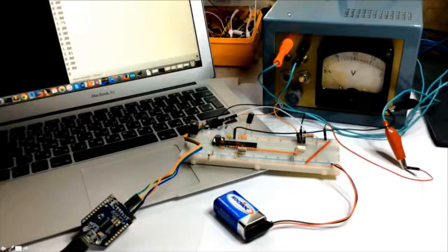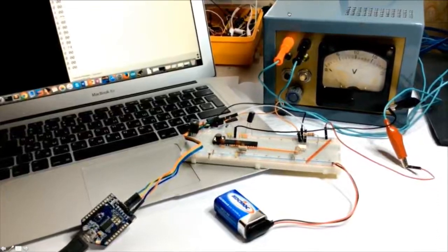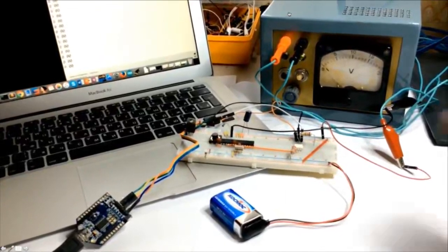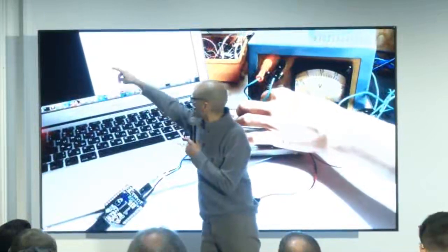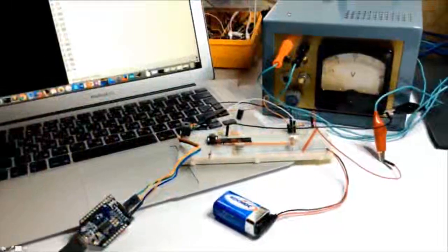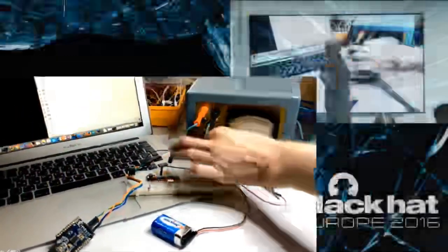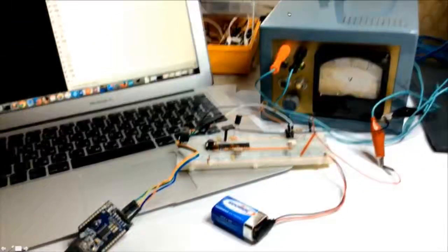And this one is actually only plain. It's a different ADC, integrated in one board. So here we have the 4 or 5 channels connected. The 5 volts is the reference, and then when we start injecting the negative value, we see that there are some weird readings on different channels. For example, the one that was reading 3.3, that was actually the reference level from the standard diagram. We were able to affect it. So instead of reading 3.3, which would be the actual value, we were able to change the reading of the ADC just by attacking a completely different channel. So we didn't really need to access it.